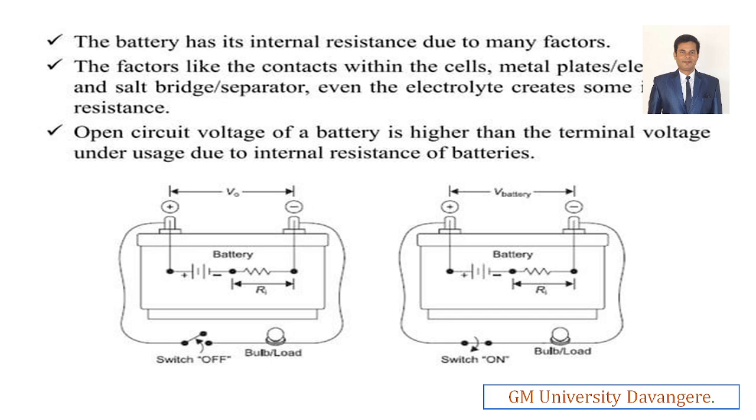And the electrodes also, like the separators between the two electrodes, and the electrolytes, can create a small internal resistance. So all these together we consider as the internal resistance of the batteries, right? So the internal resistance of the batteries may come from the metal plates, the electrodes, the salt plates and separators, and the electrolytes, and these are the various internal resistances of the batteries.